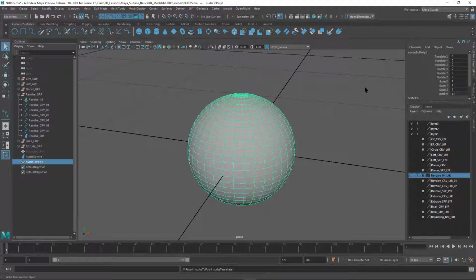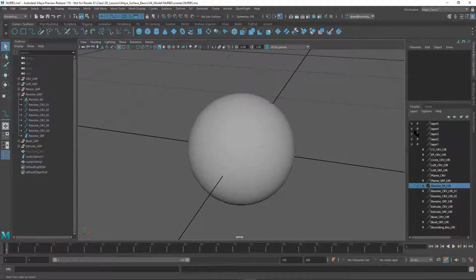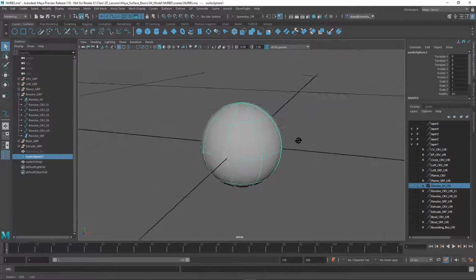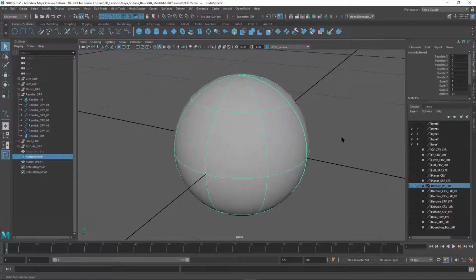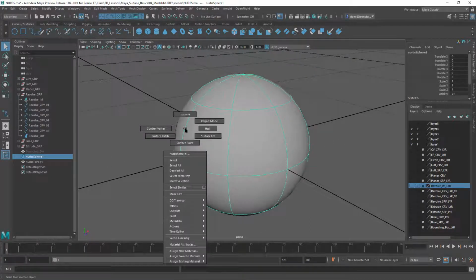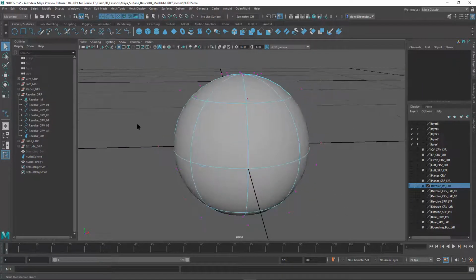Something that's kind of interesting here. Let me put this on its own layer, so it'll be layer 4, and the polygons on their own layer, which would be layer 5. Let me turn off layer 5, which is the polygons. Let's see if I still have that history thing on. Okay, let's check this out. I'm going to right click on this, so I'm going to actually get to some of these control vertices. I'm just going to play with these here.